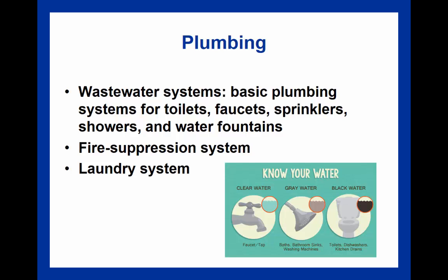And then finally, making sure that the fire suppression system is tested, that the fire suppression and response plan is tested, and that the employees understand that approach, and whether or not the facility has fire and carbon monoxide alarms throughout the facility, and whether or not those are being tested to make sure that they're not running out. So risk management is certainly an important aspect of fire suppression systems and making sure that the facility is adequately protected and adhering to their duty of care.